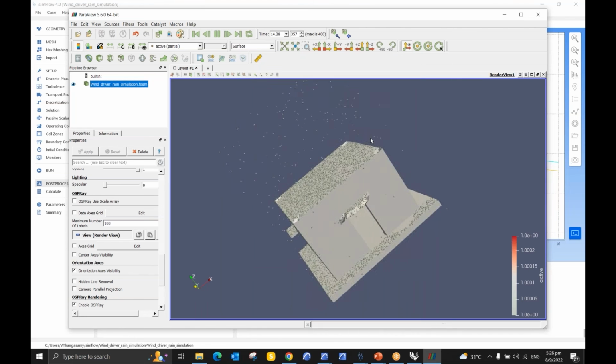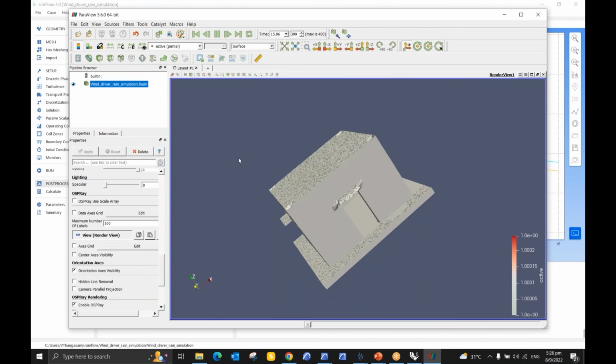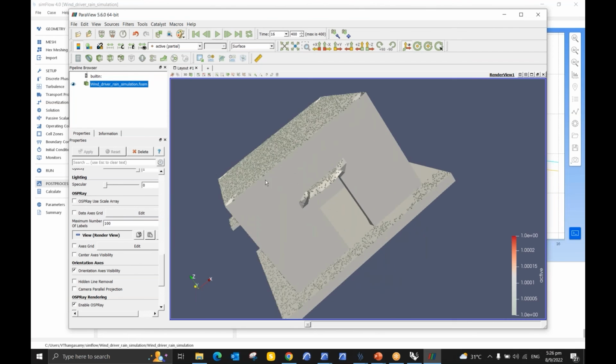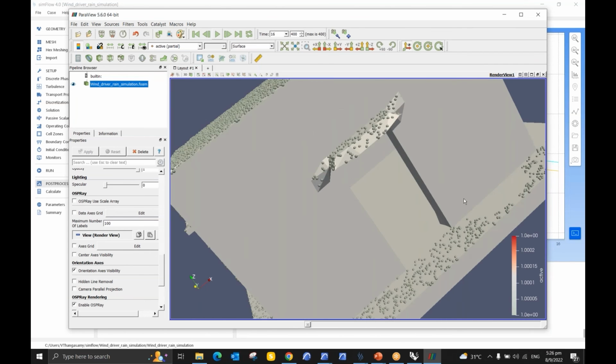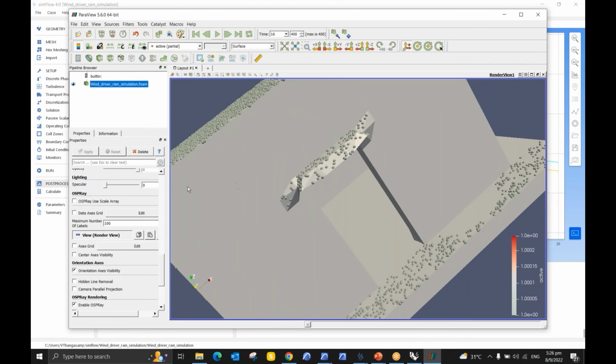This particular simulation that we are doing doesn't take that much time because it's just hitting the building and then the simulation stops there. We are not letting the droplet flow around based on the slope of the building. So you can see here the simulation has stopped already. All the droplets are just sticking to the building, and you can see here there is a shade. Since it is falling from this direction, this side is not wet, because we have the shade here.